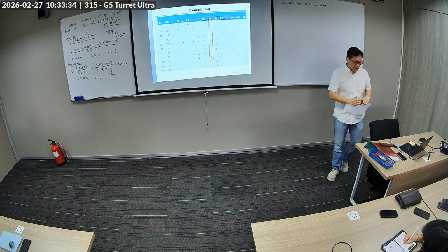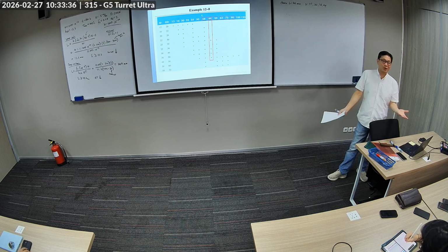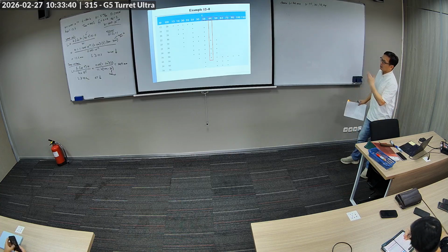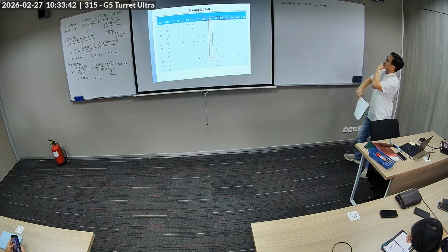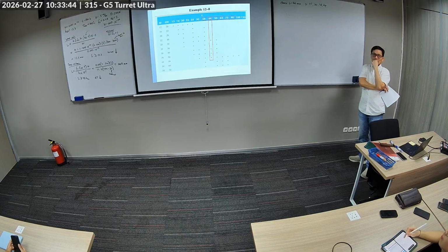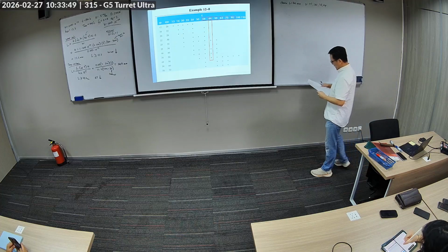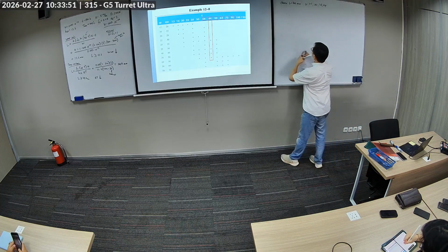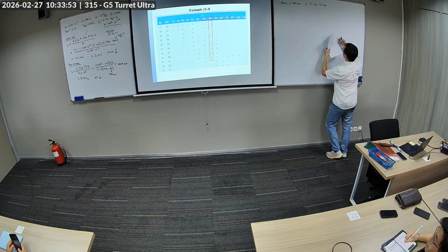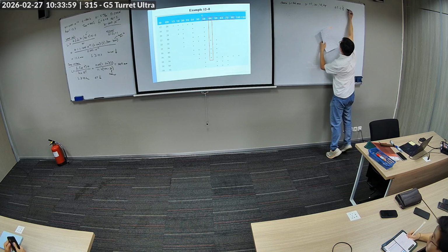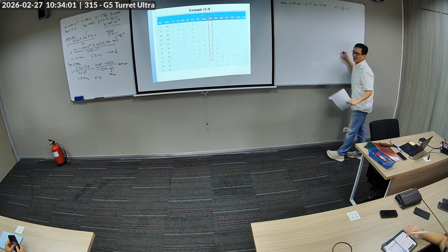Now, I know in reality, many times the diameter is already determined by a shaft, but this is a hypothetical design problem. So you are up for these four selections. First of all, there is the general design guide, right? The general design guide is that L over D should be somewhere between 0.5 and 2. This is just a guide.